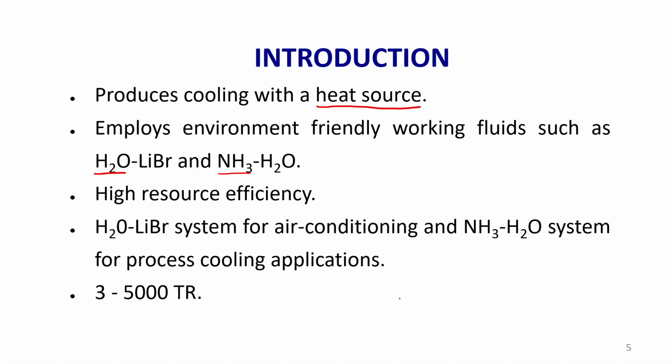Whereas in the case of an absorption system, the system does not use electrical energy except to operate the solution pump and the auxiliary devices. If the condenser and absorber are air cooled, power is required to operate the fan, or if it is water cooled, then the cooling water pump will consume a little amount of power.